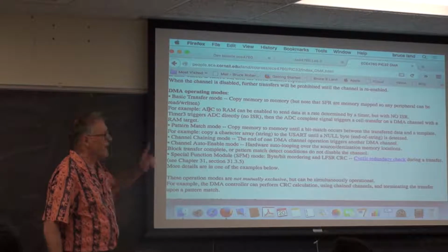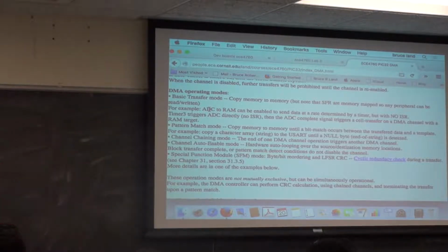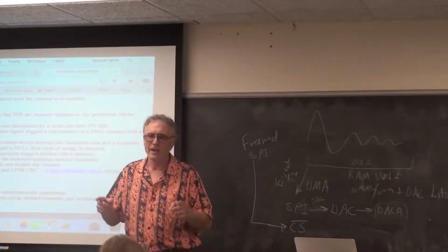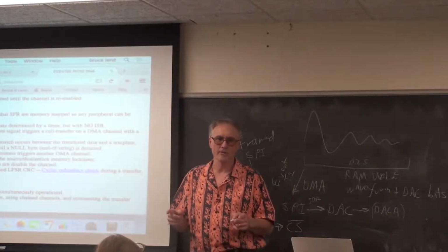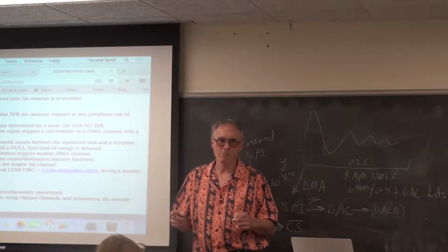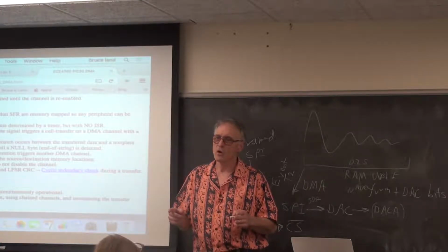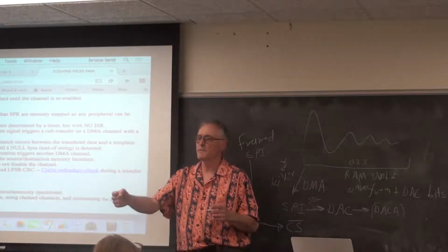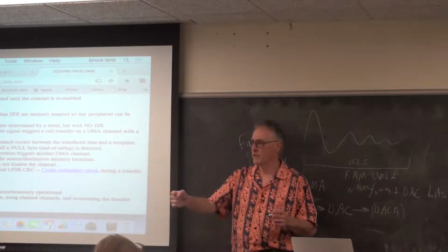There's a pattern match mode. A DMA channel, separate hardware, separate from the CPU, can do a compare between the current byte being transferred and a template byte, and if it matches, stop the transfer. So let's say you turn on a DMA channel to send a byte stream out of a serial port.